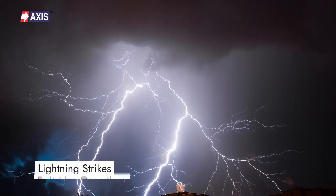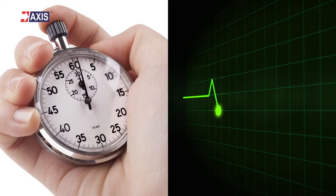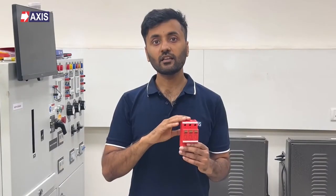Surge voltages, often reaching high kilovolts, are transient. This means they occur in very small time but with high energy, which can damage your equipment. These are caused by lightning strikes, switching operations and electrostatic discharges. Since these surges last from a few microseconds to several hundred microseconds, their short duration and high amplitude can cause sudden voltage spikes. SPDs are designed to protect against these spikes.